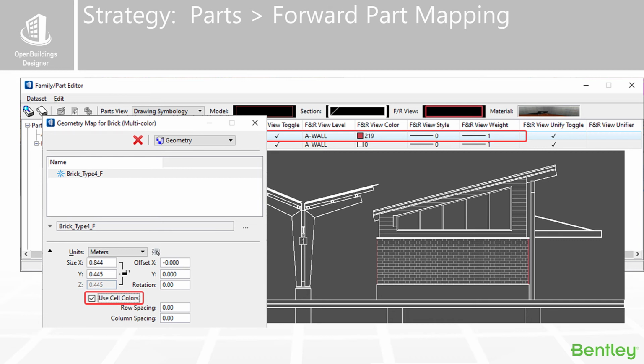In this drawing, I can still see the red lines on the edges of the wall, but the pattern map itself is grayscale because it's based on the actual cell color. That's an option. I often like to gray out my patterns. I don't really want them to show as dark as, for instance, the line work.